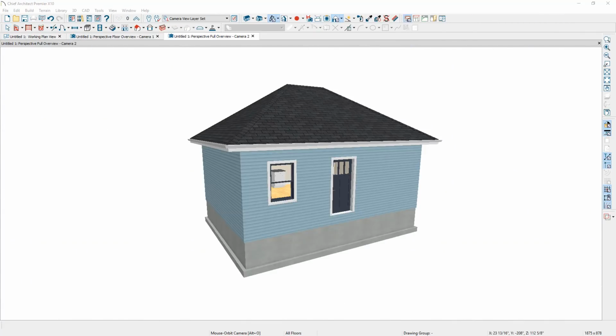This new simple plan that we created was using the residential template, and the doors, the windows, the roof, and the foundation type are all derived out of that template file. These are all things that you can pre-configure and change in your own template file depending on how you do your construction or design techniques in your locale. Let's make a couple of changes in here, and then we'll save this as our template plan.